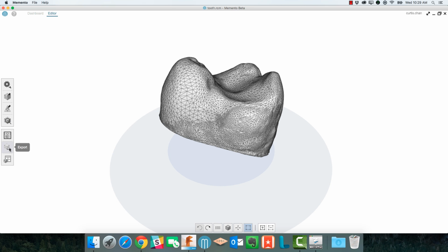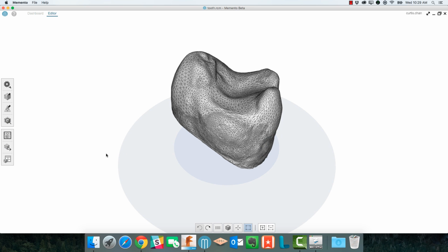Also, to keep it simple, is export. Once you have trimmed the fat that you don't want off, now it's exporting it and getting it out to a workable file we can bring inside of Fusion. So under Export, go to Export 3D Model, and then we can export it off.